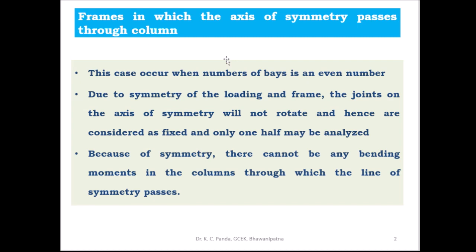What are symmetrical frames? If the frames and the loadings applied on them are symmetrical, first of all, there cannot be any side sways, and secondly, the bending moments in the frames would be symmetrical. Therefore, it should be possible to make use of this advantage, analyze only half of the structure, and by taking advantage of symmetry, express the values for the other half.